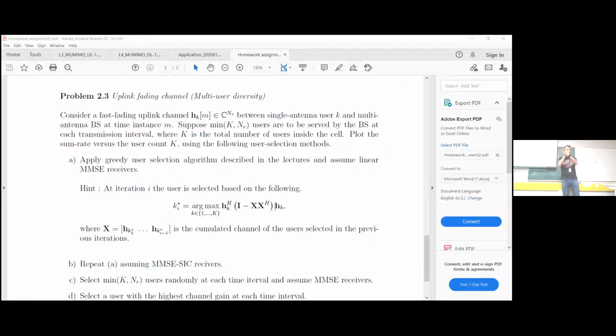This is the S. So we can now choose a point from the extended constellation, assuming the user 3 has shifted the origo, right? So user 3, for user 2, is side information, known at the transmitter. And that can be pre-subtracted using this dirty paper coding idea. Right? The user 1 is seen as additive Gaussian noise because it's encoded after user 2.